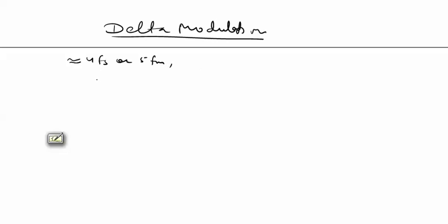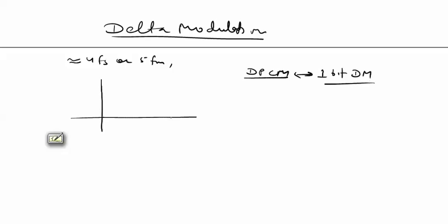The samples are transmitted as difference amounts with the DPCM scheme, because DM is a specific case of 1 bit DPCM. 1 bit DPCM means the number of levels is 2 and the number of bits required is 1.